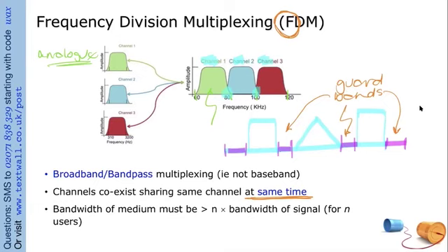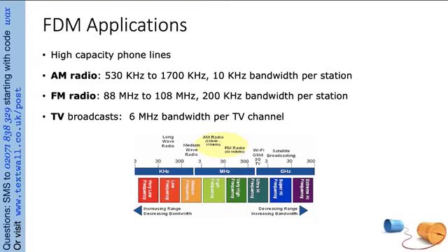If you were on a walkie-talkie and you turned to channel 2 and you were speaking to someone on channel 2, other people are still talking on channel 1. It's just you can't hear each other because you each have a different frequency channel. You're all talking at different frequencies. So you have different carrier frequencies, you might have different bandwidths. So that was an illustration of frequency division multiplexing.